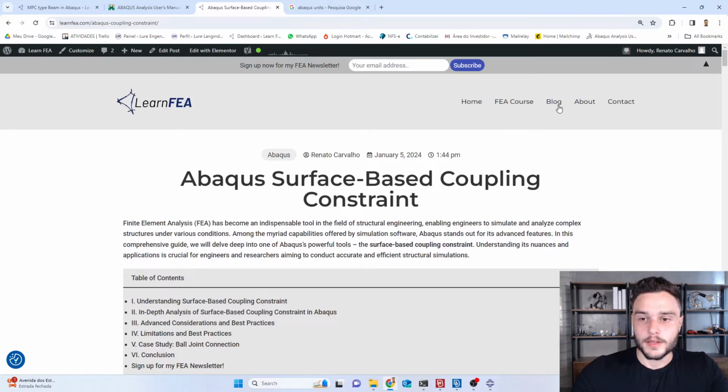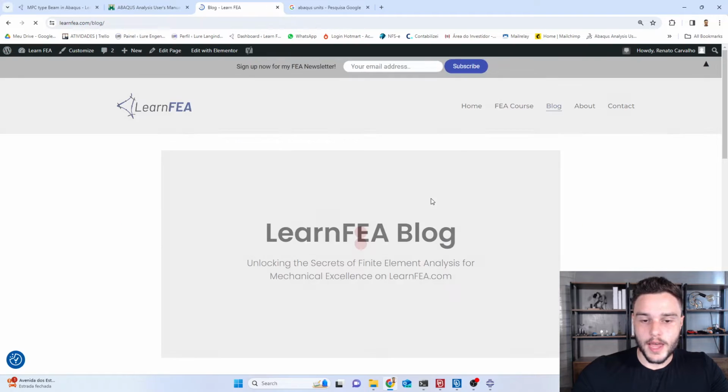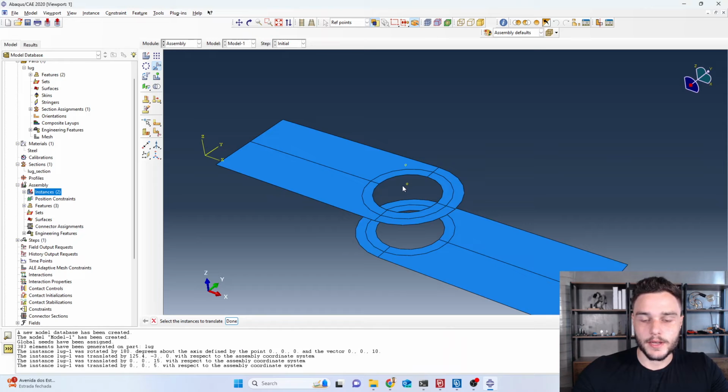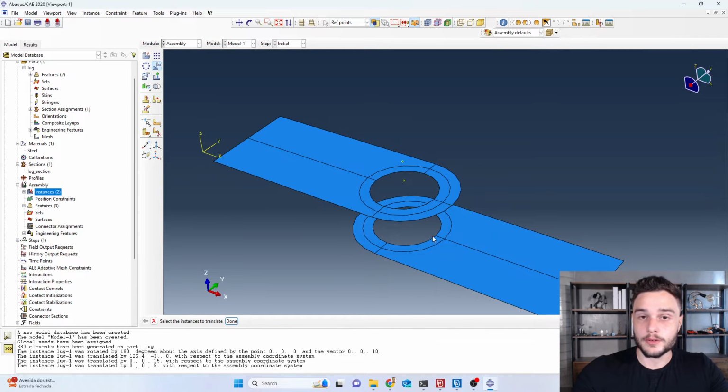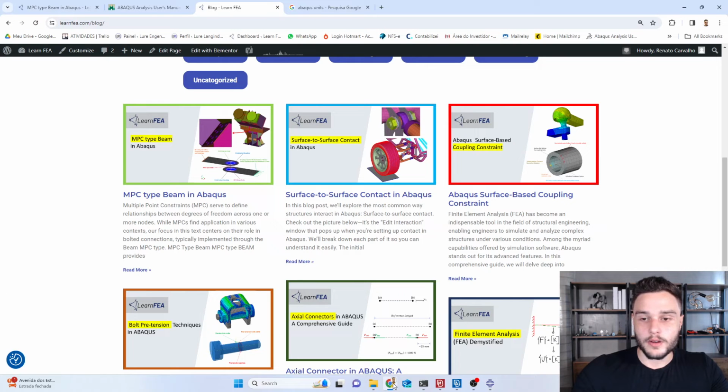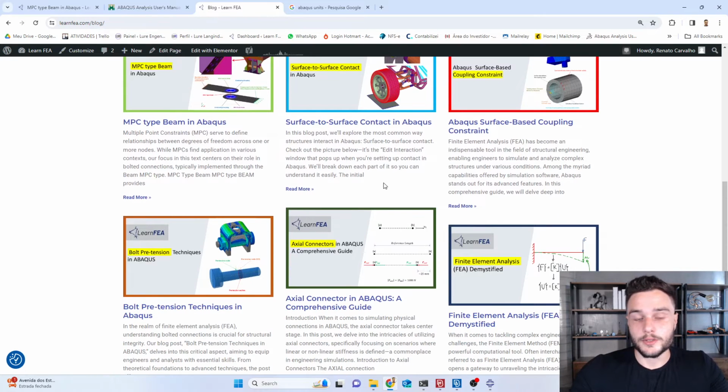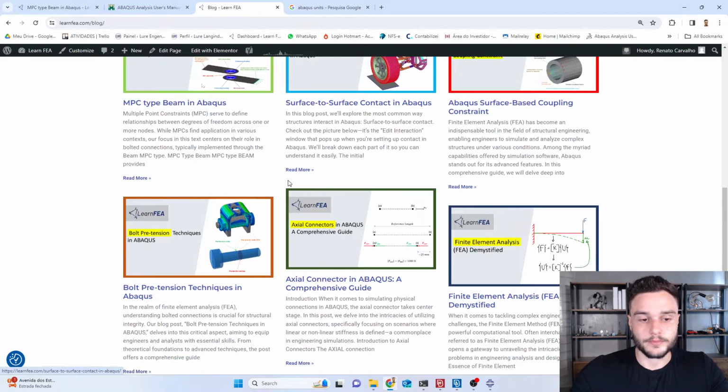Also, I have mentioned before that this type of technique is used to simplify bolted connections. However, when we want to analyze the bolted connection itself or regions around it, we should represent it using bolts, the bolt, nut, and washer, define the contact between the parts, and also apply the bolt pretension.